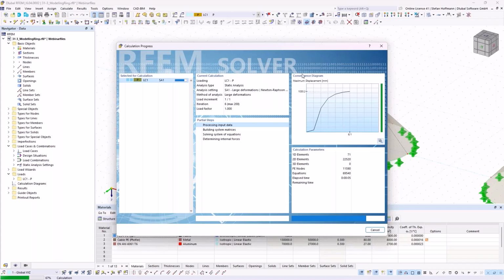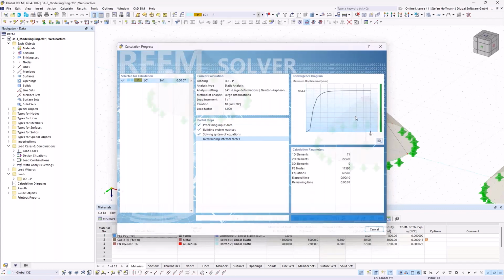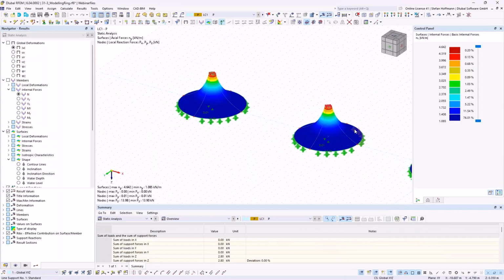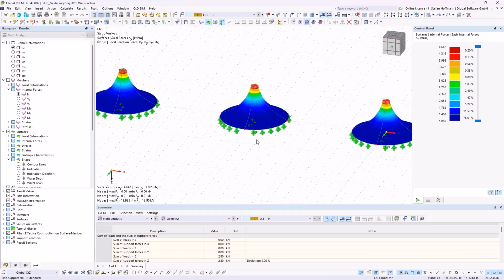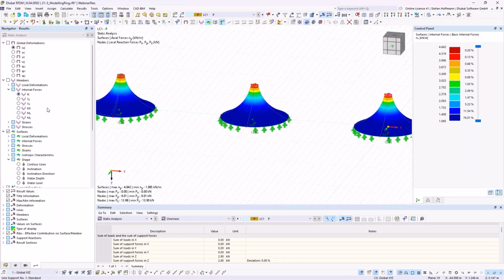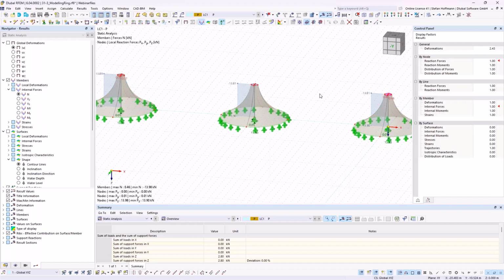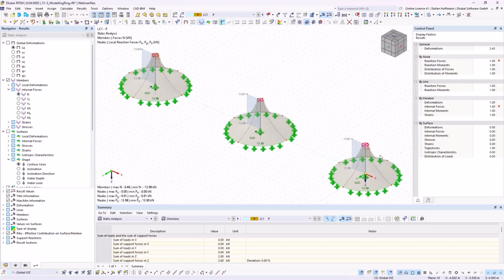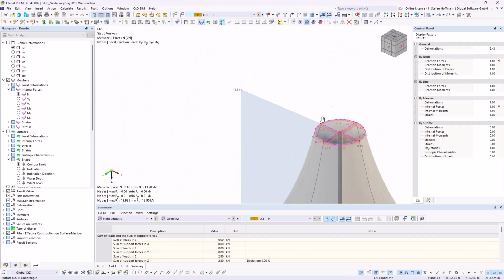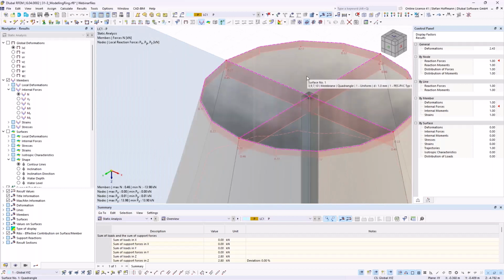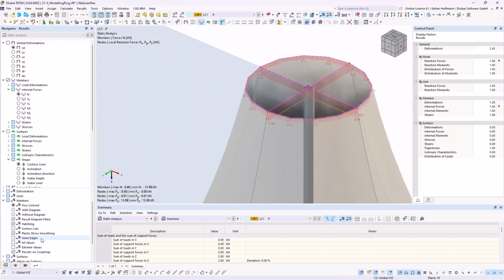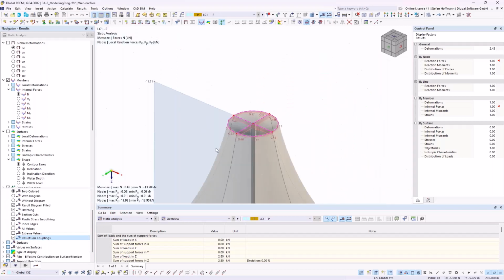Sometimes you need temporary supports depending on the numerical stability of your file. For this, we don't need them. We can see that the deformation should be similar, and also the inner forces. But then the member forces can, of course, differ from our rigid connection over here. So we have here rigid members where you can, of course, also display the results on couplings.